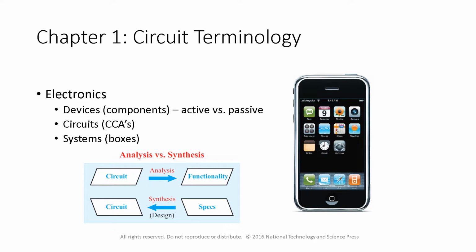So they look at the camera circuit, for instance, and they design a circuit for that camera. They look at the microphone, maybe, and they design a circuit for that. And each one of these comes down to a very separate circuit that's designed. After these circuits are designed, they will analyze them. And analysis can be with multimeters, plugging individual pins into the circuit to measure the actual voltage and current at those specific spots. Or it could be a simulation on a computer where you have a circuit design and you run a simulated current through it. And that gives you the output, which is your functionality.